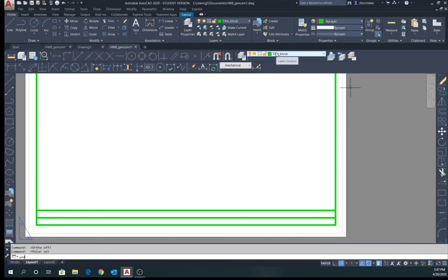Let's go back and undo this. Actually, instead of undoing, let's delete this line and go back and repeat it. So again, we start from here. We're going to move up to get a tracking line, type 0.5, slide over. We see our tracking line. And with polar tracking, you now see we have the intersection point. So we need to have polar tracking on in order to get the intersection with that line, not just the ortho tracking.